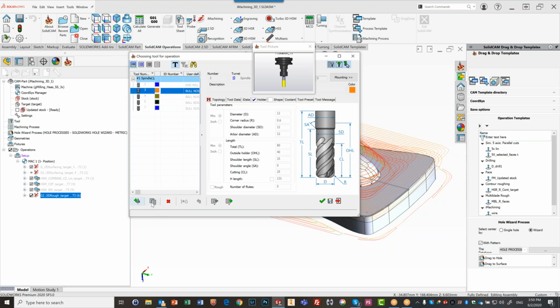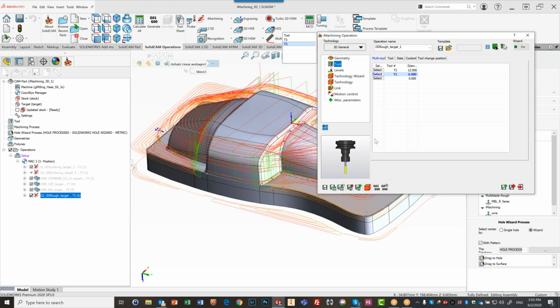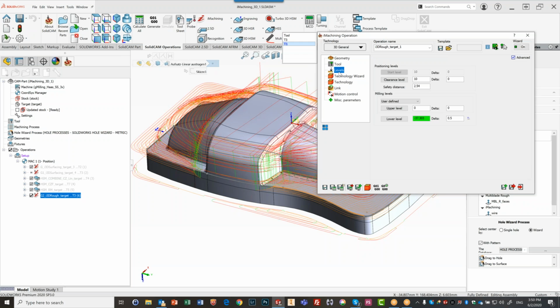I'll show him. I'll just create a copy of this tool. I'll have this here as 6mm. Okay? I'll have the radius over here as Radius 3. There we go. Okay. Levels, I'll keep that the exact same thing. Oh, wait, the level, it's right, the same operation. Now you'll see now this, I'm in tool 1 over here.